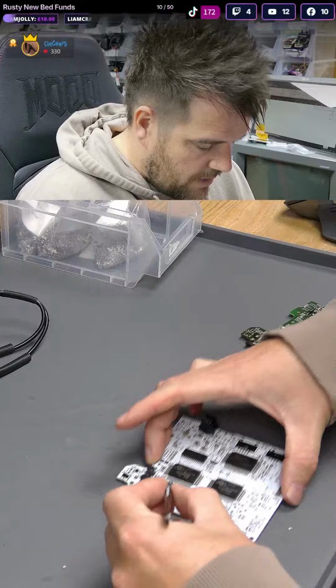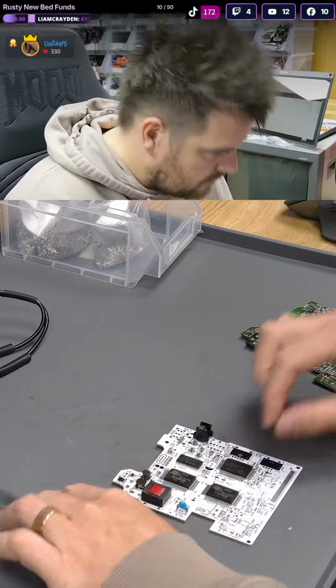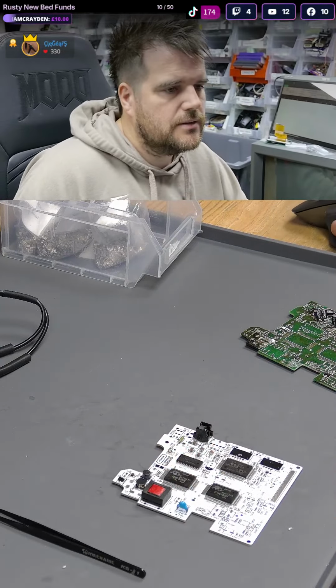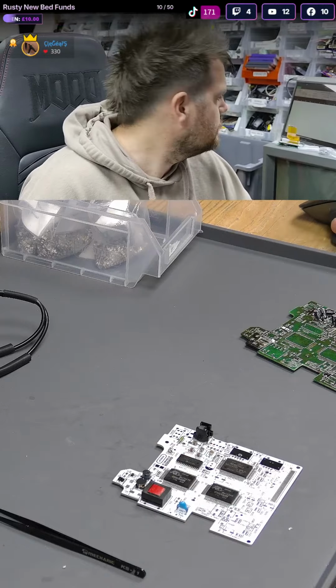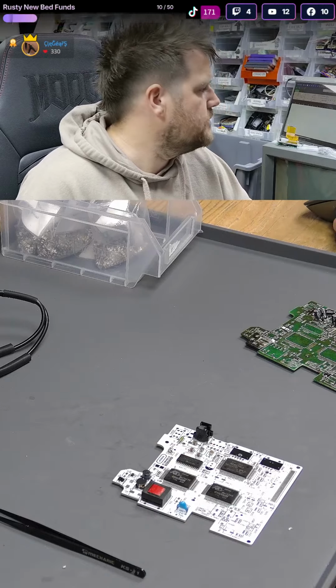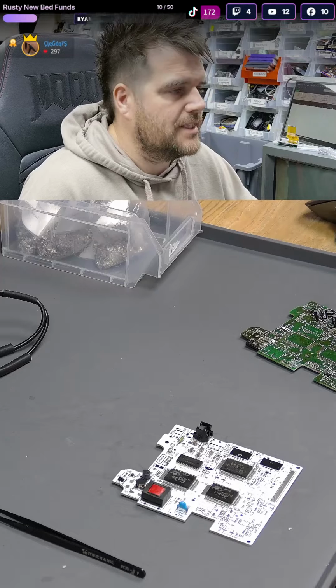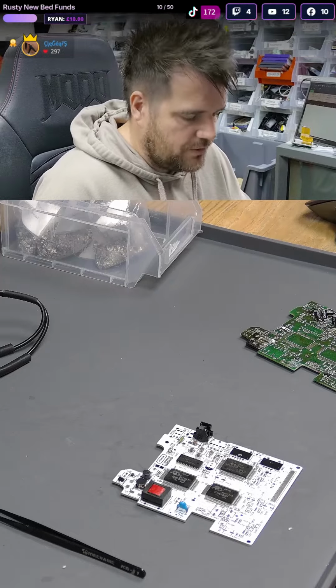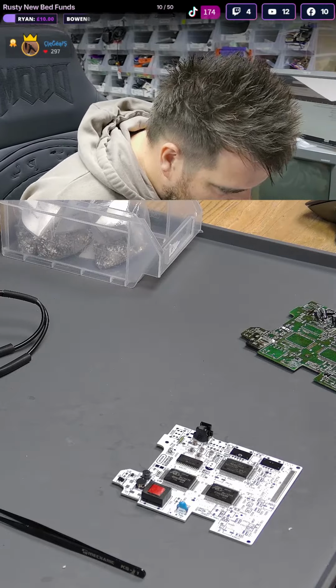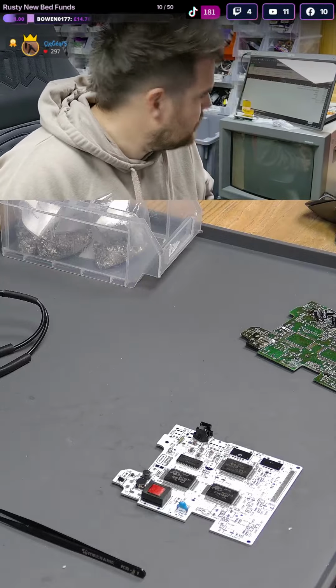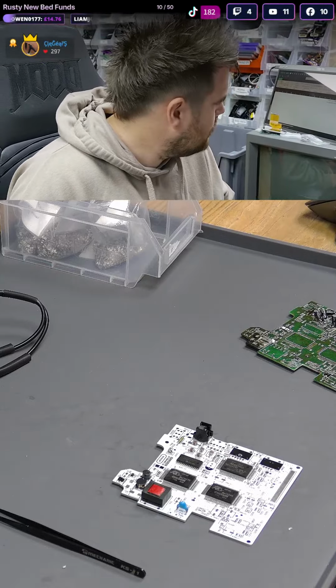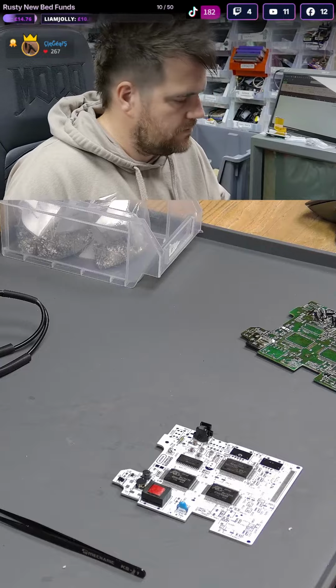We can chuck him back on the circuit, we'll place him there in a minute. I'll just make a note before we forget. We don't need to make a note of the other caps because I've got the cap kit. I'll add that to the bill of materials when we're done, so I literally don't need to write down those ceramics we just put on. But C703 is 0.1 microfarad.